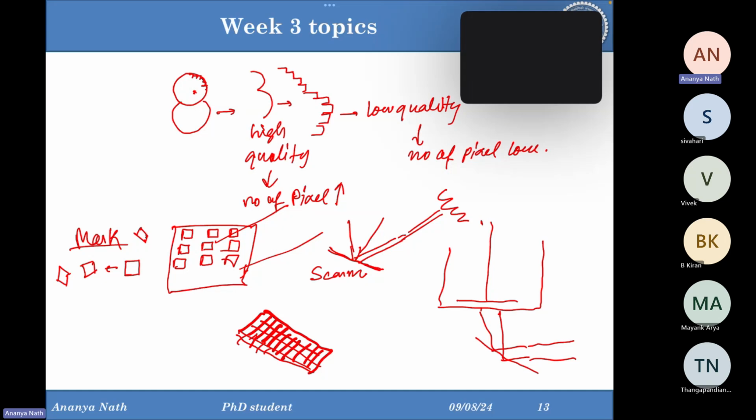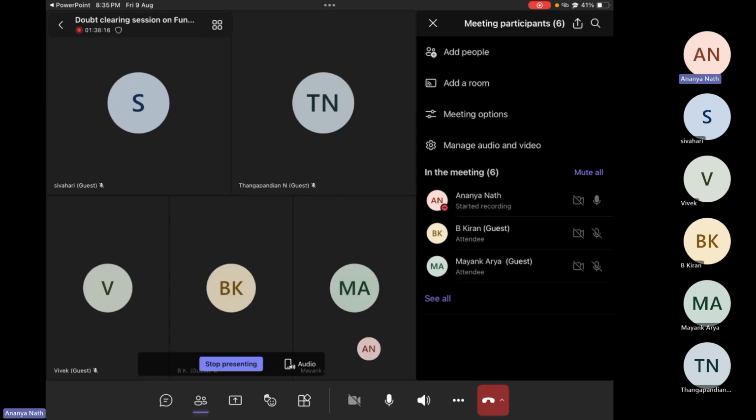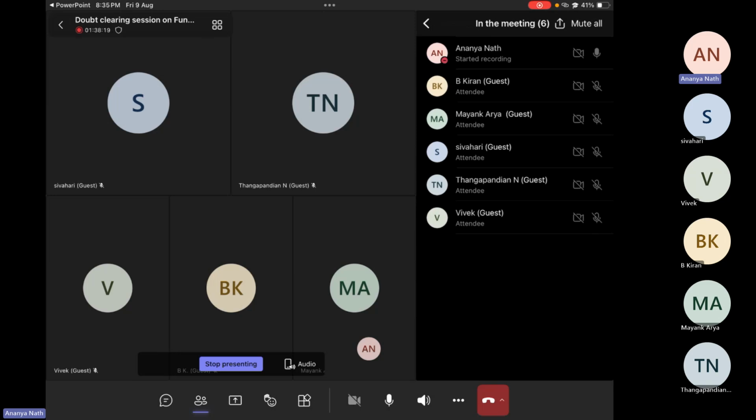So all the mirrors will not reflect the object onto the build plate. Basically they will make a projection of light on the build plate, which is called the mask. And on the projected area, the resin will get solidified. So this is the concept of projected light DLP, and LCD based DLP comes under wet photopolymerization. If you have any doubt in this topic, you can ask me.